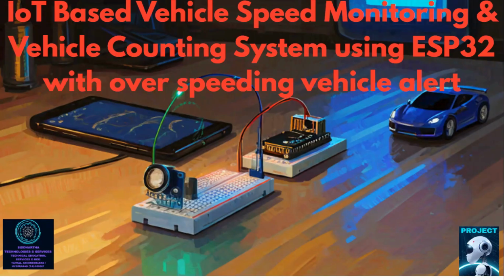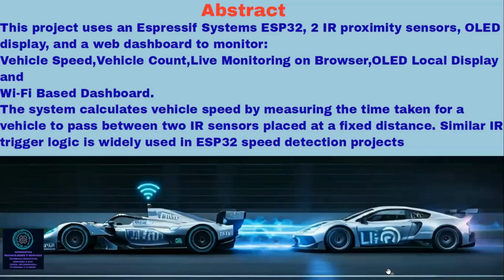The name of the project is IoT-Based Vehicle Speed Monitoring and Vehicle Counting System using ESP32 with Overspeed Vehicle Count. What we are going to see in this project, let's see the abstract part first. This project uses an Espressif ESP32 board with two IR proximity sensors, an OLED display, a small display, and a web dashboard to monitor. What we are going to monitor: vehicle speed, vehicle count, live monitoring on browser and OLED screen also, and a Wi-Fi based dashboard. That is the IoT part.